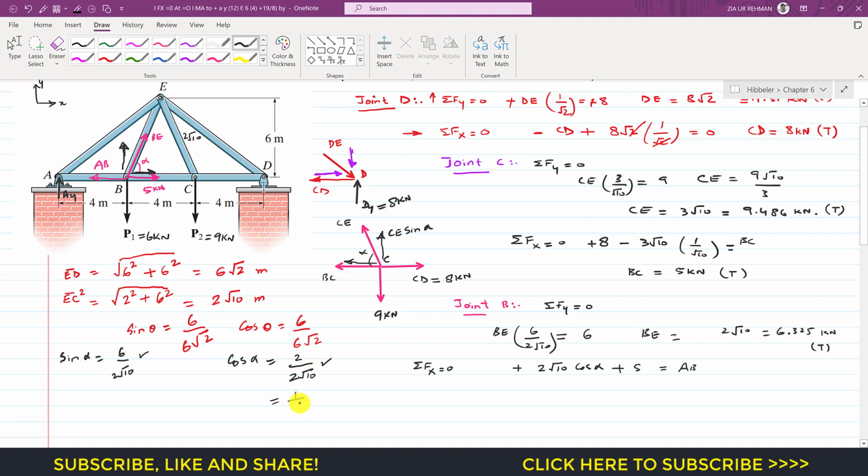So cos of alpha is 1 divided by square root 10, so I will write 1 divided by square root 10 is cos alpha, and this will cancel out. So AB is 5 plus 2, so this is 7 kilonewton. So AB is 7 kilonewton, and AB is again acting away from that joint B, so it is the tension force.